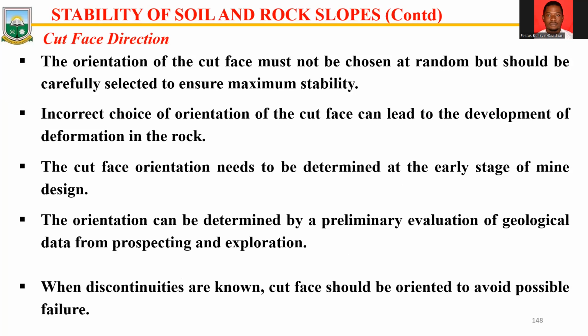They have stated that if we want to be on the safer side during the exploration and prospecting stages, we should come up with the various features and discontinuities that are likely to occur when we pick out our drill core, to give us the information on how our discontinuities are oriented, and that will help us to choose the best cut face direction to avoid this failure.